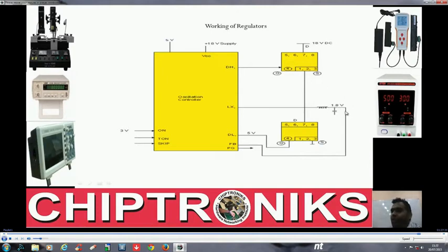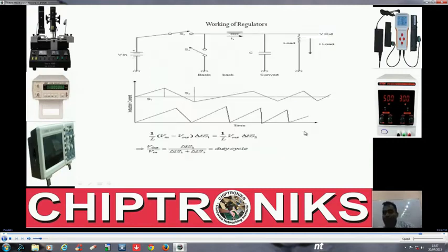Feedback is given so as to check whether we have got the right output at this point or not, so that with the feedback the regulator will drive the drive high and drive low signals to generate the required output voltage. So you got how the output is generated. Vout by Vin is delta T S1 by delta T S1 plus delta T S2. This is also called the duty cycle.